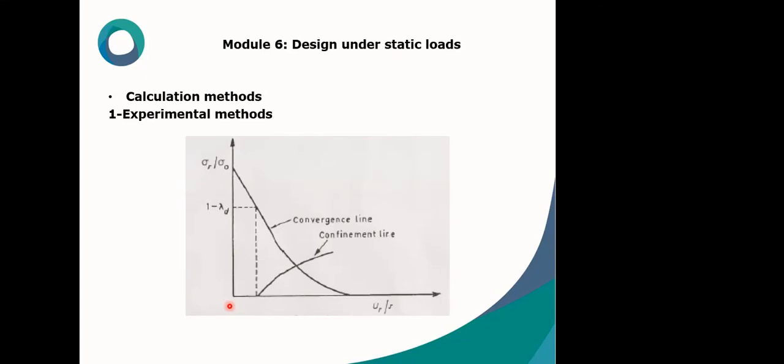Another point to explain will be the simple method to conduct two-dimensional modeling. Tunneling construction, in fact, is a 3D problem and will require some tricks for simplification. Numerical modeling usually analyzes the plane strain condition.